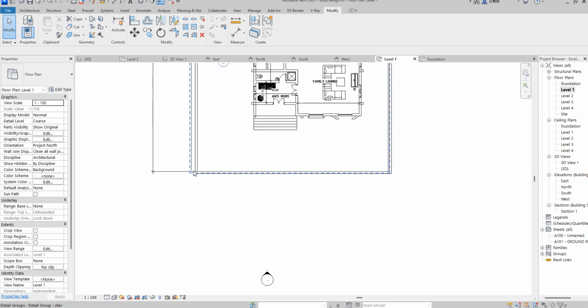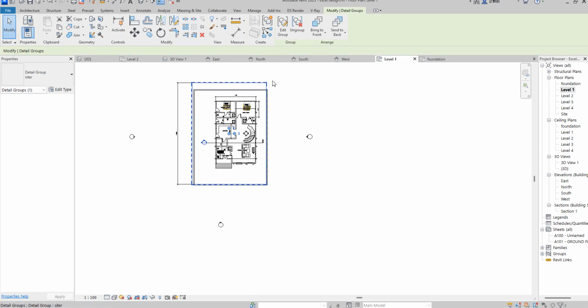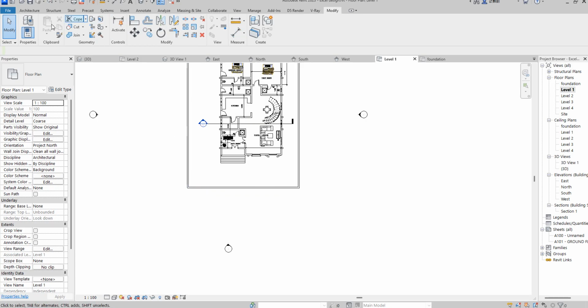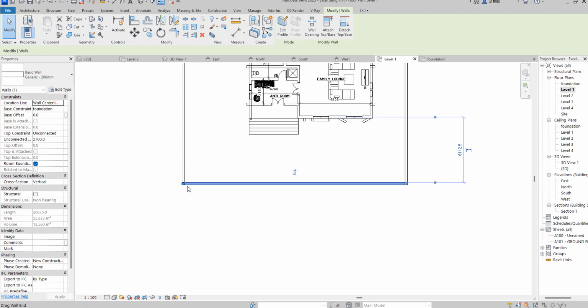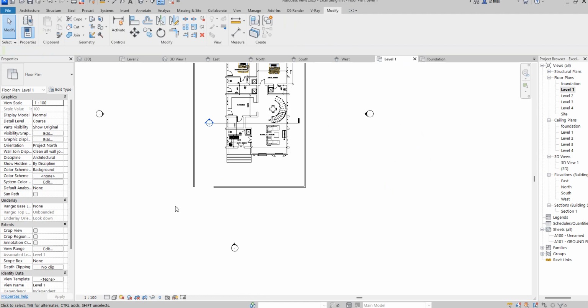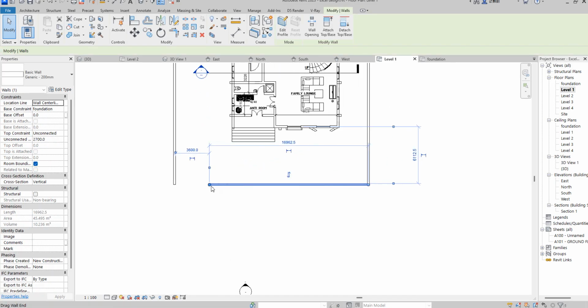And so we do things here. So remember, this is the detail of the site that we had before, so you can delete it. It's not needed anymore. Now we come here and say click here, adjust this so that we fit in the gate position. So your gates will be 3600, 12 feet used to be the standard gate, so fix at that level. So the point is that the gate of this face may be a little bit not reasonable. The reason is that you have a swimming pool here, so you cannot be entering and enter directly into the swimming pool. So you change the orientation.